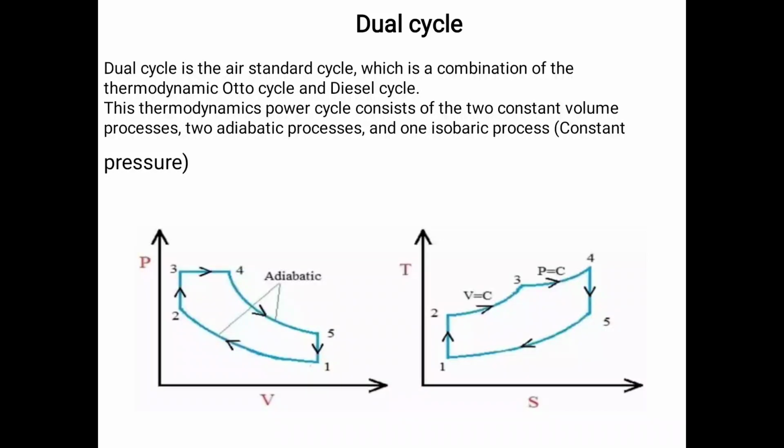From the expression for the air standard efficiency of the diesel cycle, it is seen that the efficiency decreases as the value of density ratio rho increases, and therefore it is desirable to keep the value of rho as small as possible to increase the efficiency. This can be done by supplying the heat partly at constant volume and partially at constant pressure. In an actual oil engine working on this cycle, it is obtained by injecting part of the fuel towards the end